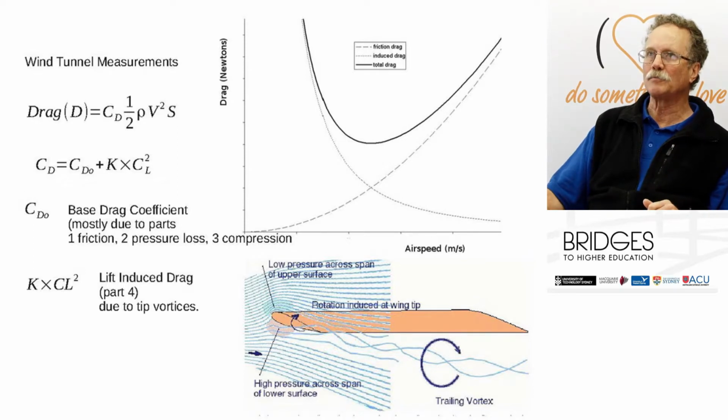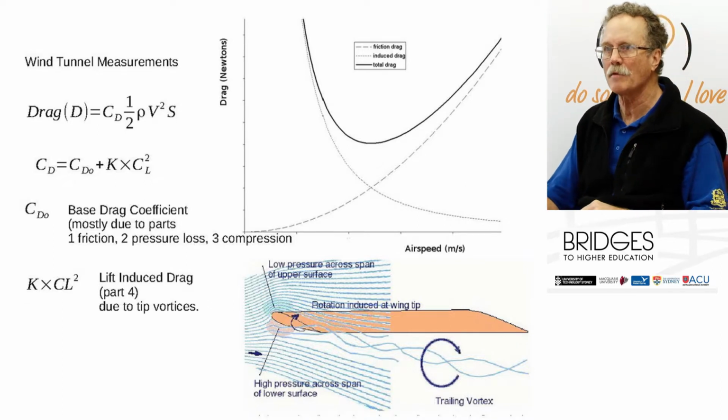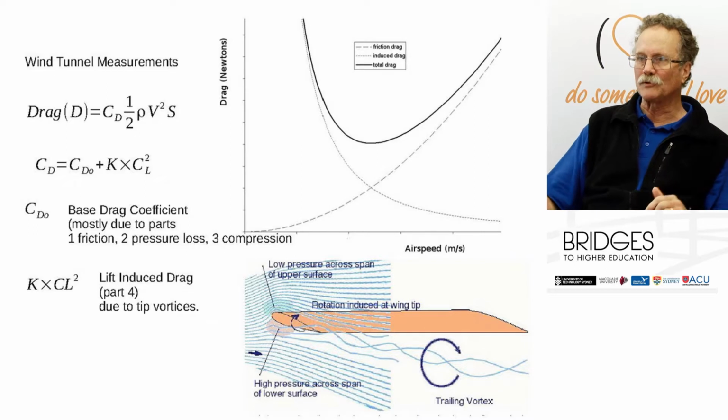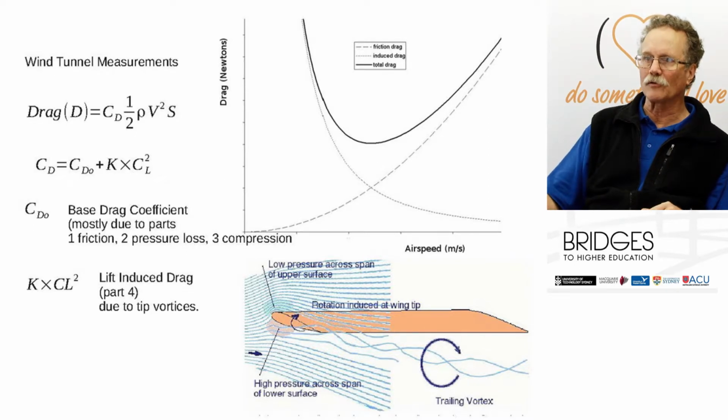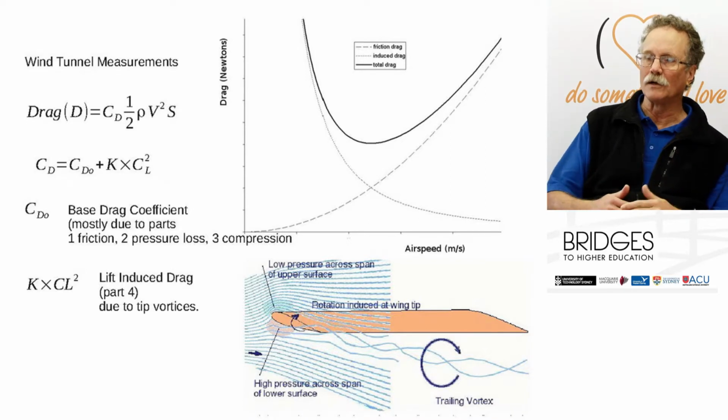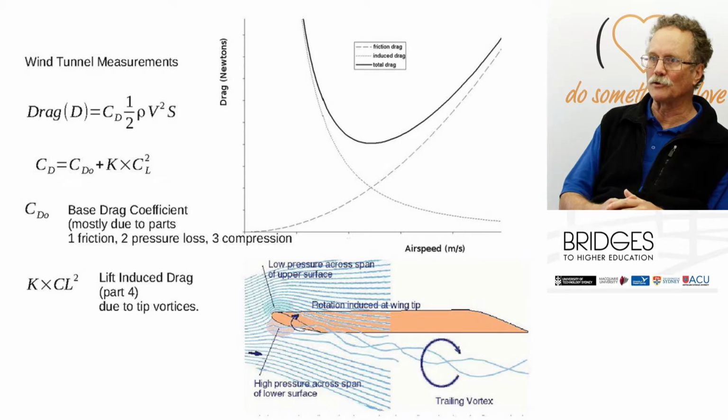Now this low speed drag is a complication due to producing lift. So if you can see it, down the bottom we have the wingtip. So we saw the previous diagrams of the high pressure underneath the aerofoil, the low pressure on top. Now that can't happen at a wingtip. There's nothing to stop the airflow moving around between the two regions.